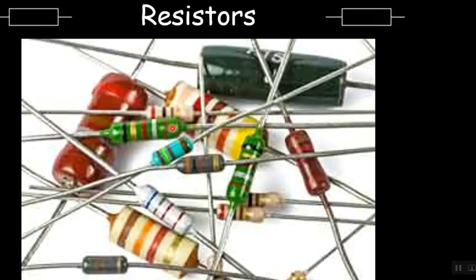Okay, so guys, different types of resistors. These are the types of resistors that we'll be using. We think that resistors don't actually build up heat, but in real life they do slightly. But if we speak about a resistor, it looks like this, and you'll see it in a lot of circuits. If you look at some circuit boards inside electronics, you'll see a lot of these smaller ones. Now the lines on them tell you the value of that resistor. The different colors have different codes, and we use those codes to label the size of the resistor.